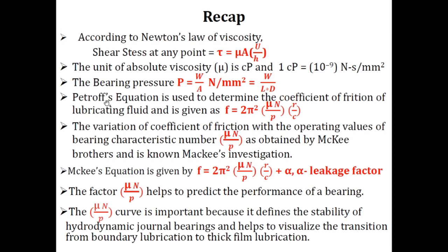We have also discussed Petroff's equation, which is used to determine the coefficient of friction of the lubricating fluids. Its relation is f, the coefficient of friction, equal to 2 pi square mu n upon P into R upon C. We then looked at the variation of this coefficient of friction with the operating values of the bearing characteristics number.